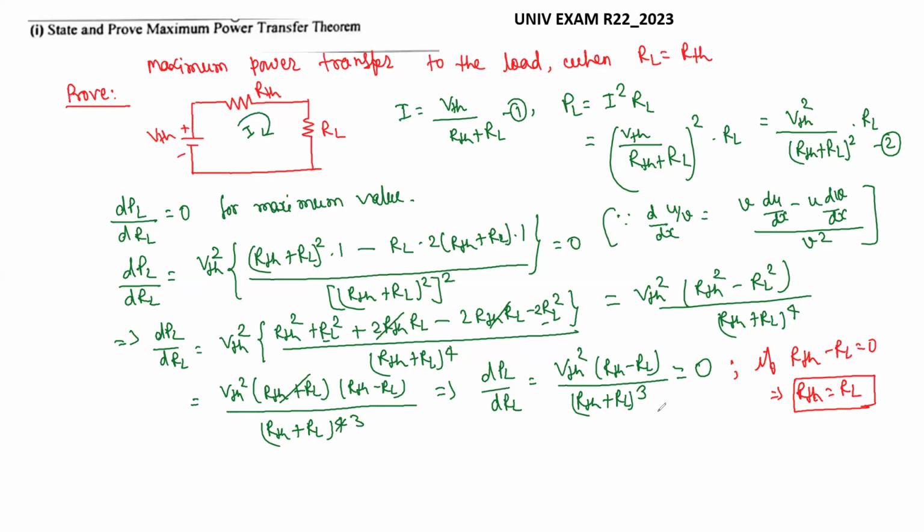And already we have the expression earlier, and again you can write, so that the maximum power transferred to the load will be PL max, that we'll have here BTH square into RL divided by (2 RL) whole square.